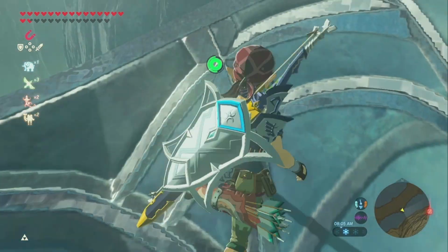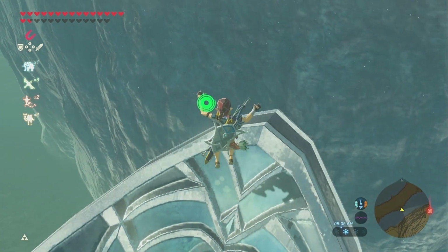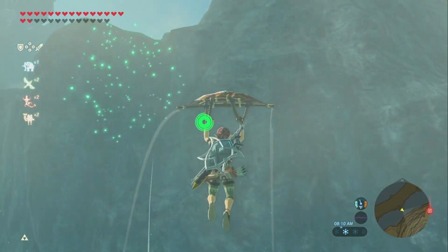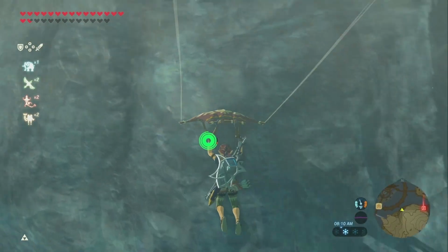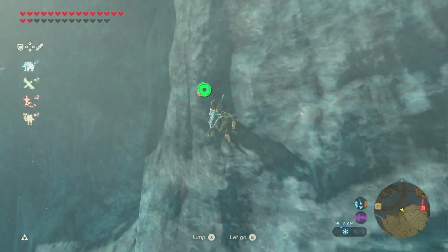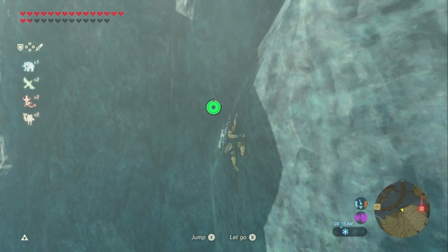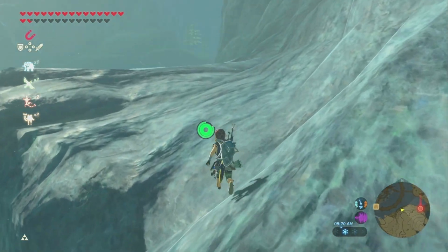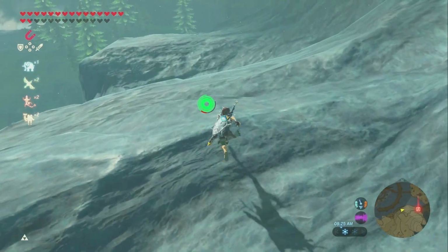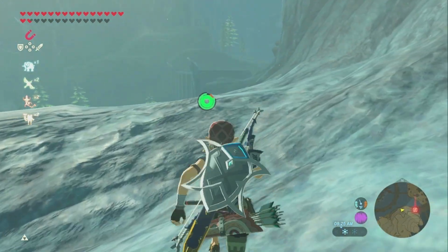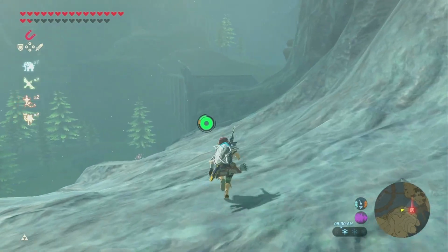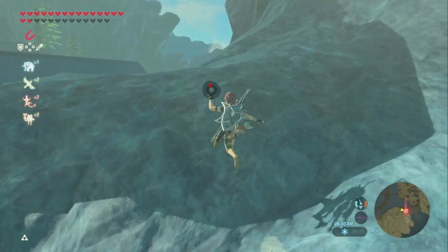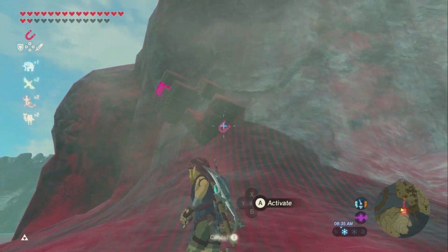Improper sidewall vent locations. Numbers vary in some areas and circumstances. Check local rules. Should be 4 feet, Canada 3 feet, below or beside doors, windows, or air inlets, and 1 foot above. Should be 3 feet from regulator. Should be more than 1 foot above grade. Should be more than 7 feet above paved public walkway or driveway.